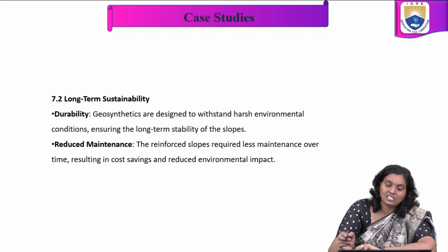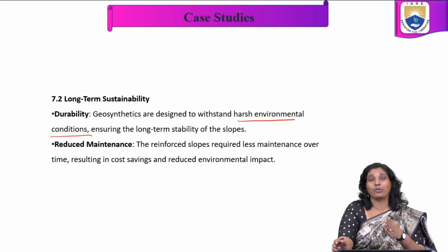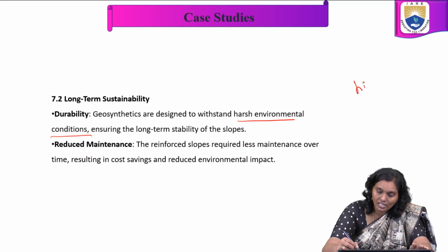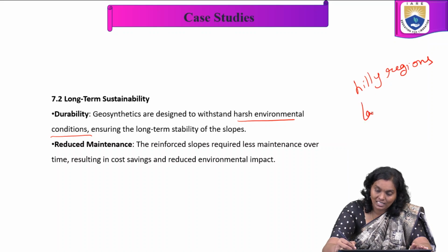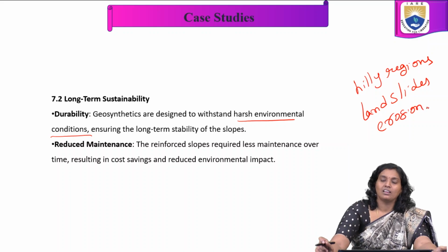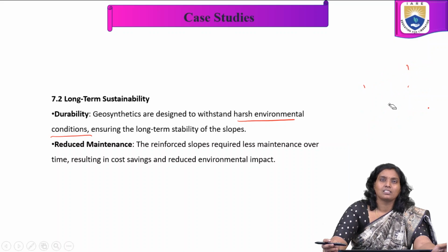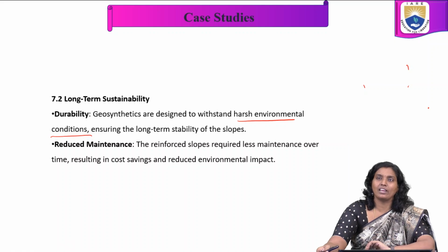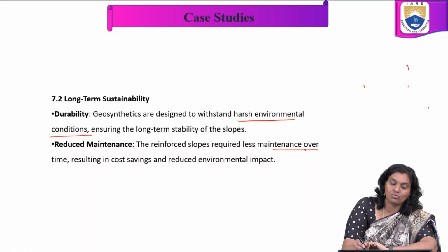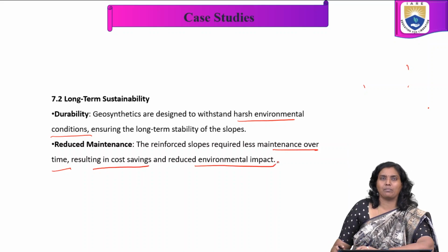Geosynthetics are designed to withstand harsh environmental conditions, ensuring the long-term stability of this slope because of the hilly region and the chance of landslides and erosion. These are the harsh environmental conditions for this case study. With reduced maintenance, the reinforced slopes required less maintenance over time, resulting in cost savings and reduced environmental impact.